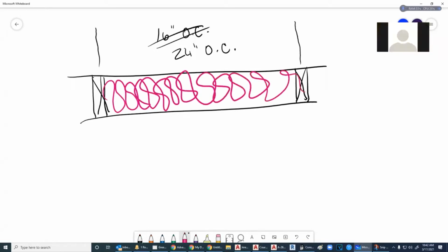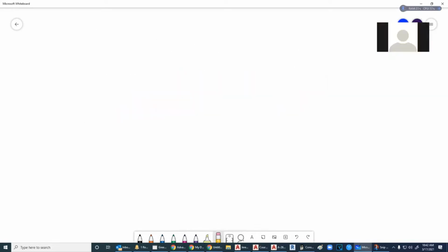So you're going to be using a 2x6 when you go to 24. Yeah, because that's load bearing, so you can't do that unless you up your stud size. You can still actually do a 2x4, but you have to make sure that everything lines up. Let me explain that. You mean you have to have your joist centered above your stud so that you don't have so much weight in between? You got it.